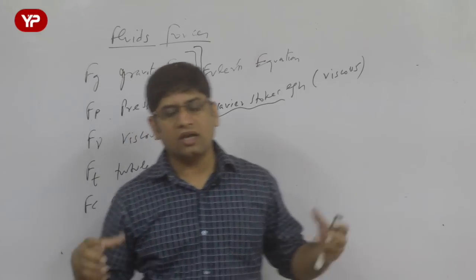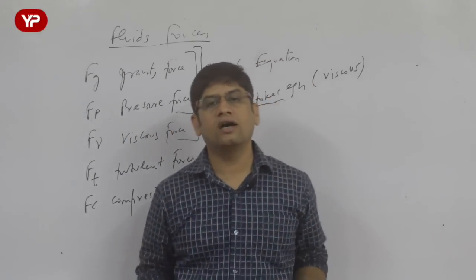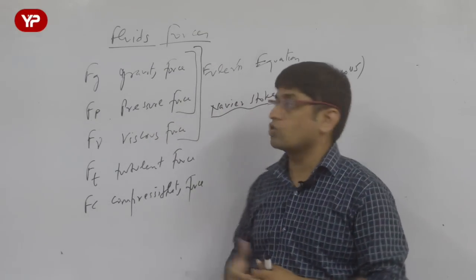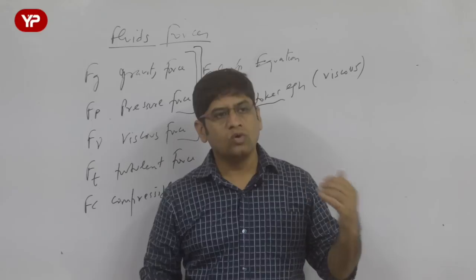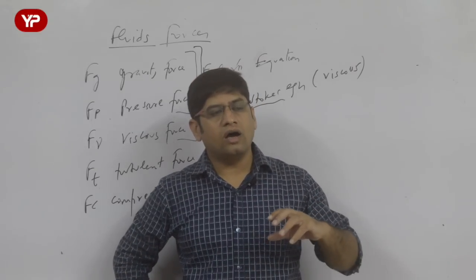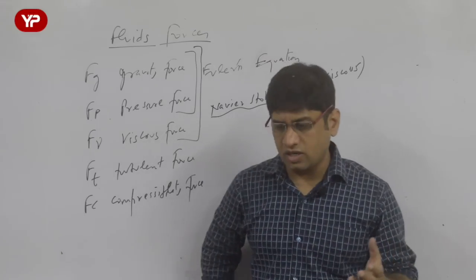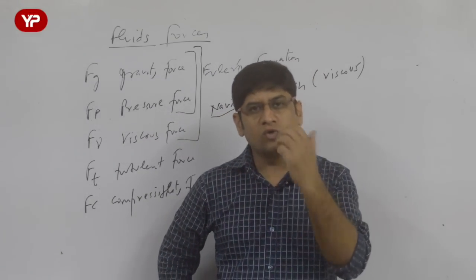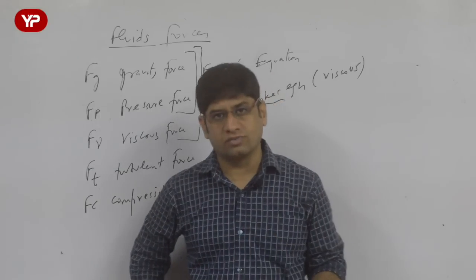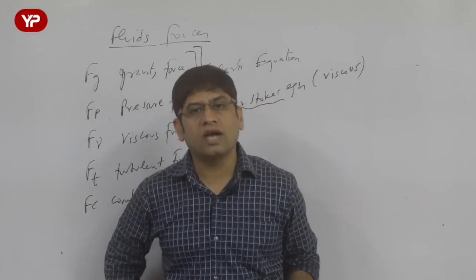And let me tell you, in GATE exam or BTech, you do not study the viscous or Navier-Stokes equation. You study more Bernoulli equation and Euler equation, because Bernoulli equation is the energy conservation equation for ideal fluid. We assume that the fluid is not having viscosity, but that is a wrong assumption, because every fluid has some kind of viscosity.